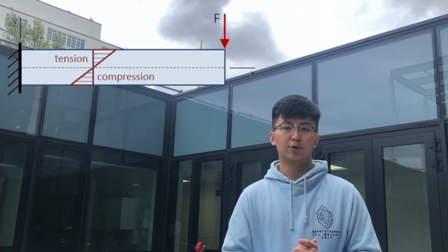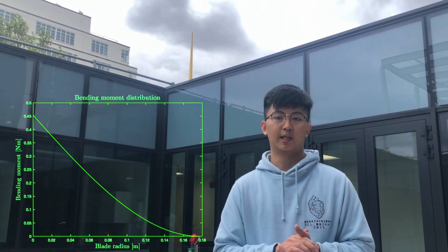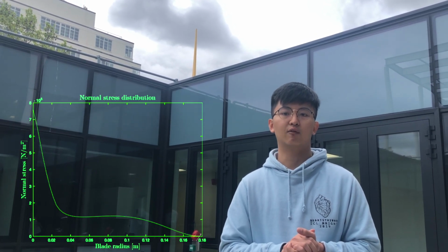Using the cantilever approach, a series of repeated Simpson's integrations were performed to find the moment distribution and subsequently the maximum tip deflection. Through the obtained moment distribution, total stresses can be calculated, which allowed us to iterate over many different blade radii, finding the optimal radius given the yield stress of ABS plastic. The radius that should theoretically produce the largest CP without failure was found to be 23 cm, which was slightly larger than the printing constraints.